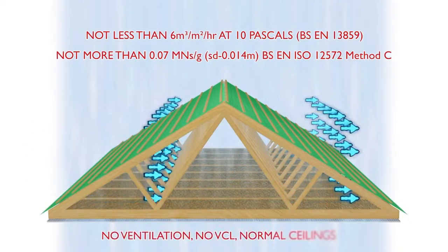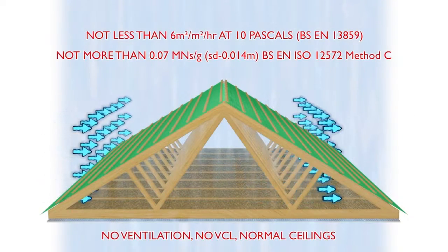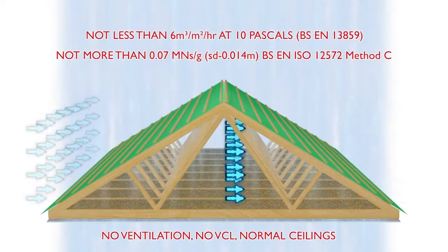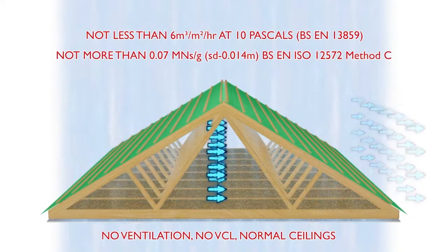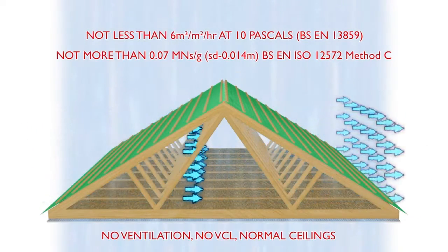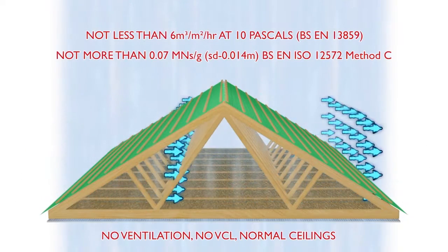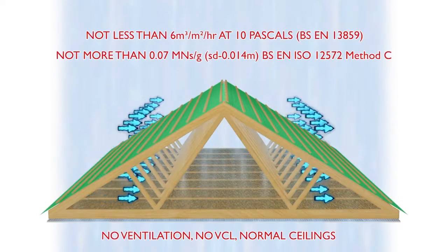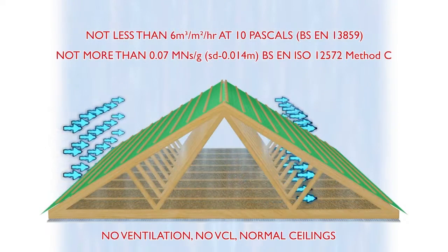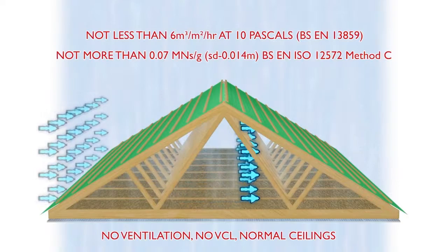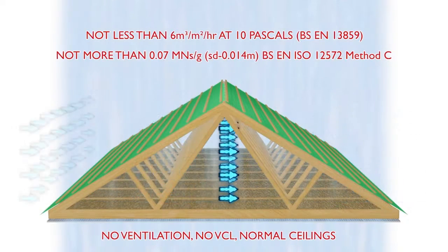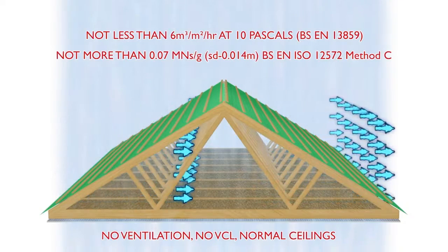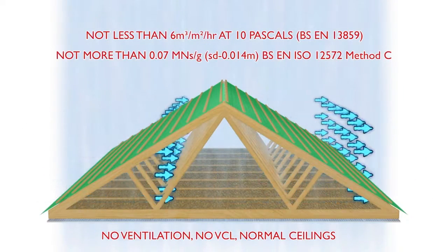Membranes meeting the specification can, however, be used in all circumstances with no ventilation, regardless of the size and shape of the roof. They also do not require a well-sealed ceiling, making this type of underlay a great choice in refurbishment applications, where the precise ceiling specification may be unknown. Taken together, these factors make APLR underlays which meet the performance criteria the simplest solution to address condensation in cold-pitched roof applications, and the only solution that can be specified across multiple projects with no changes.